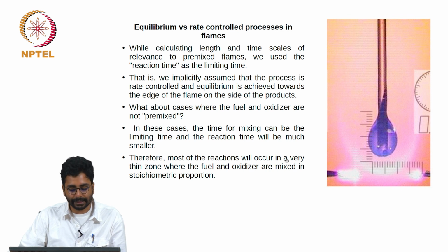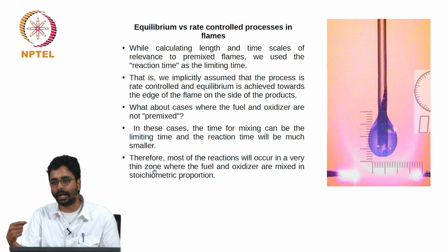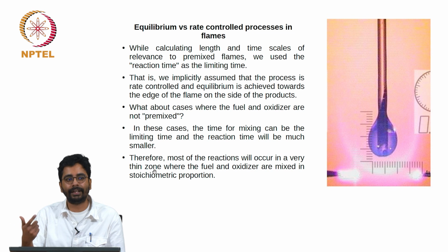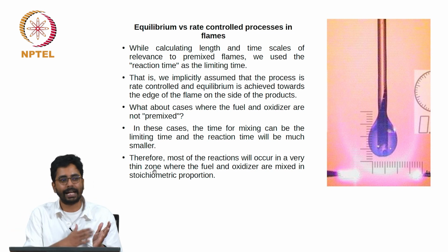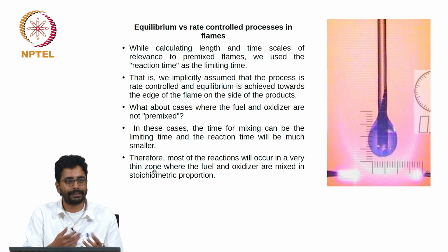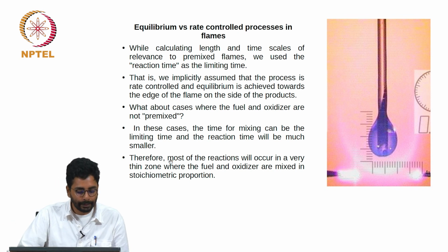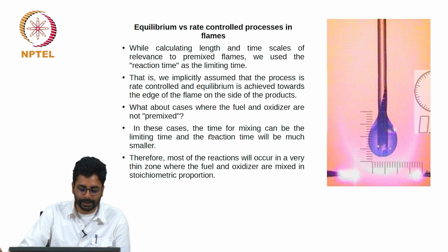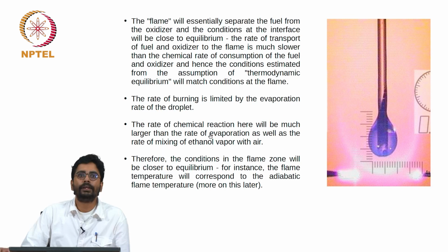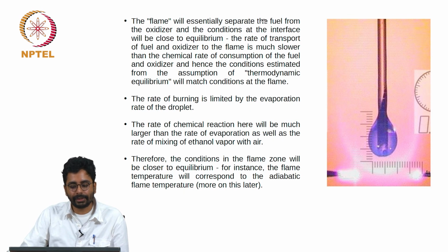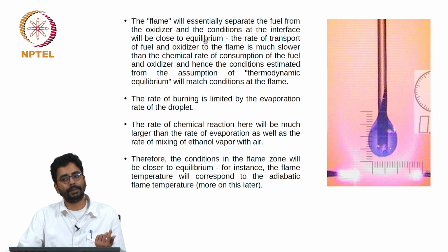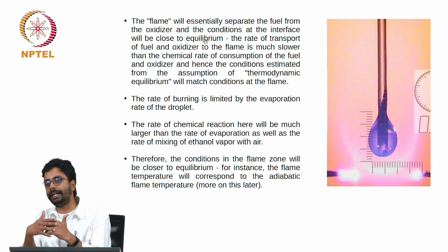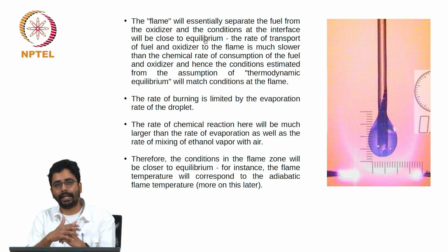Therefore, most of the reactions will occur in a very thin zone. It is not that easy to define a thickness here. If the reactions are infinitely fast, the reaction zone necessarily has a thickness of 0. So most of the reactions will occur in a very thin zone where the fuel and oxidizer are mixed in stoichiometric proportion. The flame will essentially separate the fuel from the oxidizer. In the premixed case, the flame separated the premixed reactants from the products.